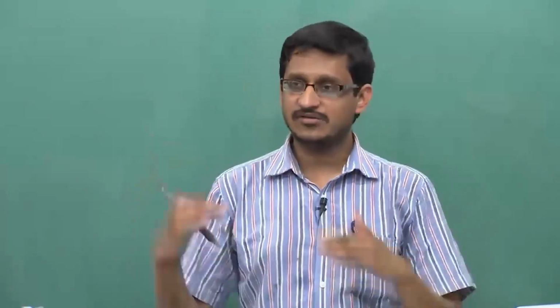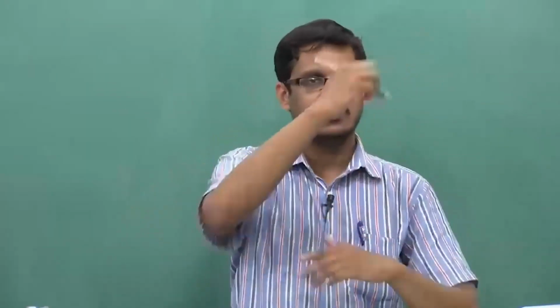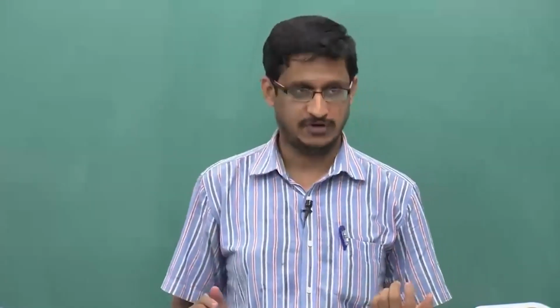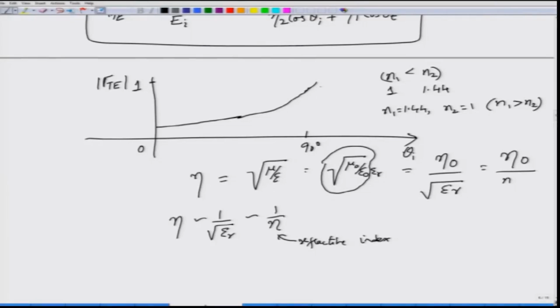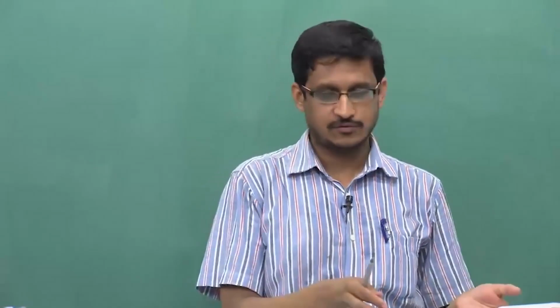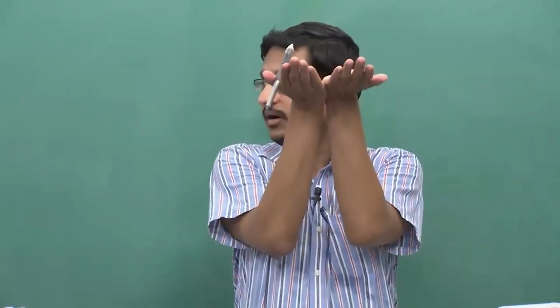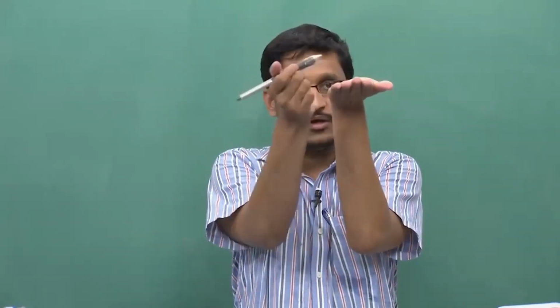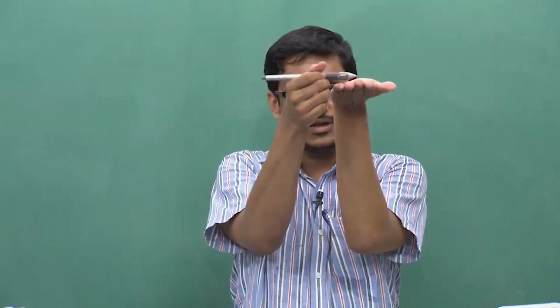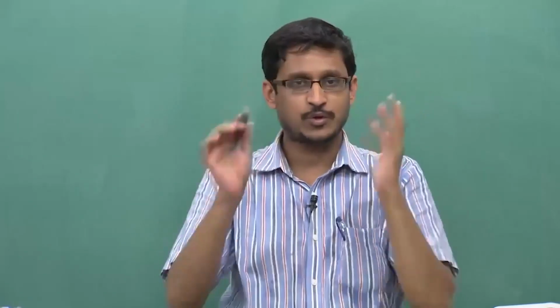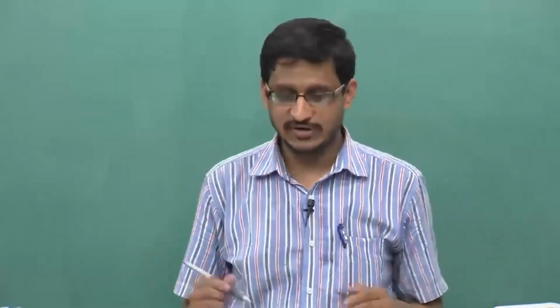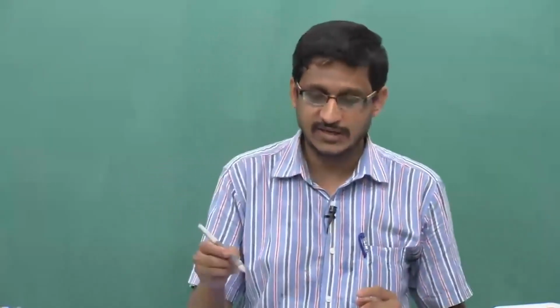Okay. This is called grazing angle incidence and transmission from the grazing angle, and this is valid for both TE as well as TM waves. So that is why at 90 degrees the reflection coefficient goes to 1, that is almost the entire wave gets reflected. You can try this. If you were to take a book and hold it up and try to read, you will get maximum reflection because light is getting reflected. If there is anything printed on the piece of paper, you won't be able to read it. So this grazing angle is something that is common to TE and TM.